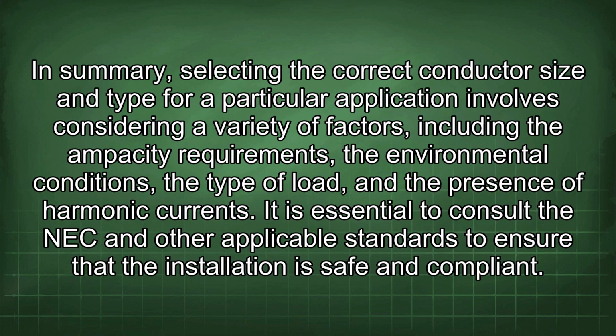In summary, selecting the correct conductor size and type for a particular application involves considering a variety of factors, including the ampacity requirements, the environmental conditions, the type of load, and the presence of harmonic currents. It is essential to consult the NEC and other applicable standards to ensure that the installation is safe and compliant.